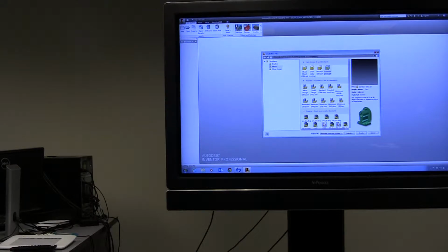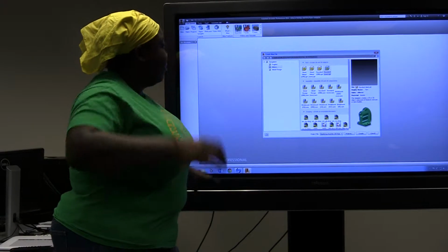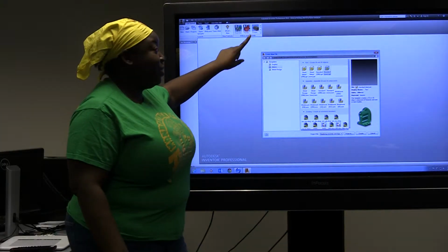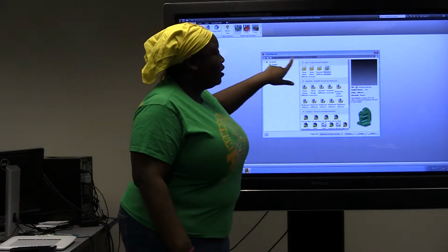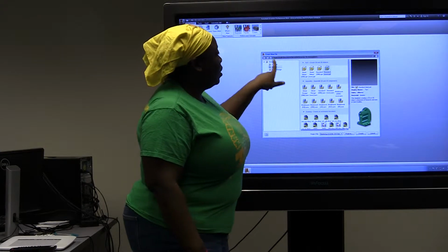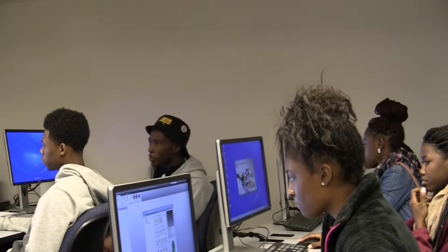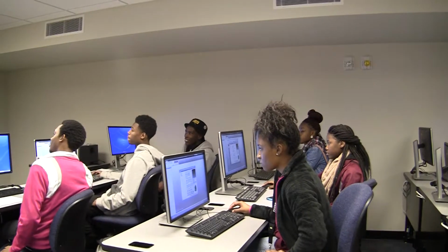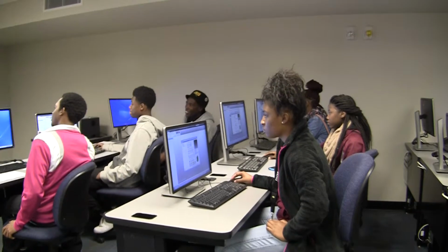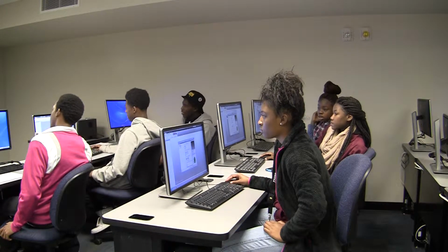Yeah, that'd be helpful. Okay, so you should be at this screen right now. What I want you to do is click on English. That's going to make sure that we're able to get into inches. Click on English, and then you'll see a little cube over at the side that says Standard IPT. Once you've selected those two, then you can click Create at the bottom. So I'm going to click Standard IPT, and go to Create at the bottom.